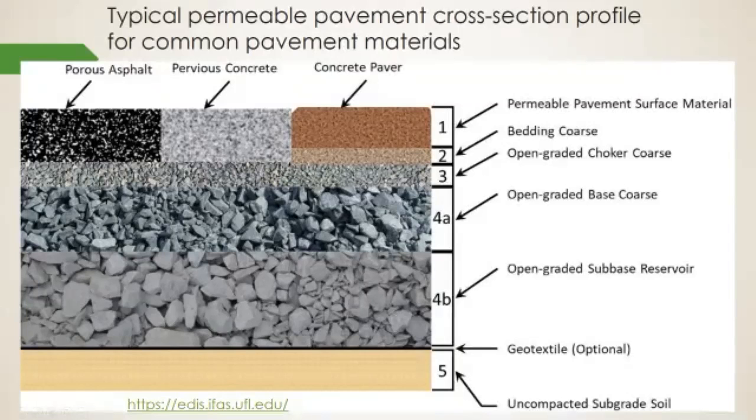So we're going from the choker, what you might call a choker course. These are courses here of gravel that the water is moving through. And the choker course is going to help with filtration. This is going to help with holding and filtration. And then the subgrade is basically, and not all of them have this subgrade, this is maybe for a more intense, complex build. Often for paths and residential, we're just going to do the choker course and the base course. But this is putting it to the next level with the reservoir area if we're looking to hold a lot of water, a high volume of water. And so maybe this would be something in a place like Florida, somewhere like that, where they get higher volumes of water during tropical storms, something like that.